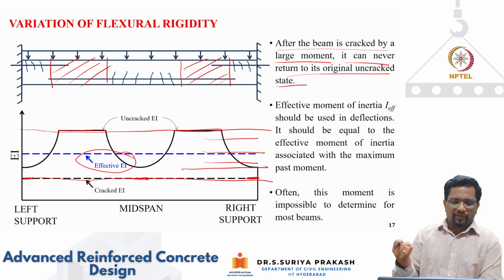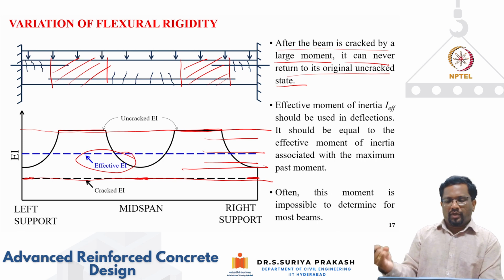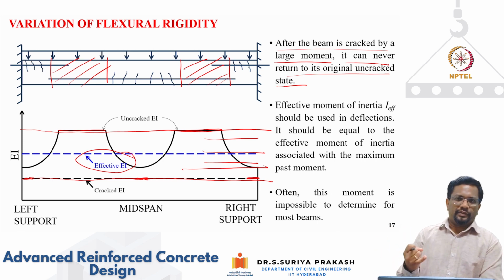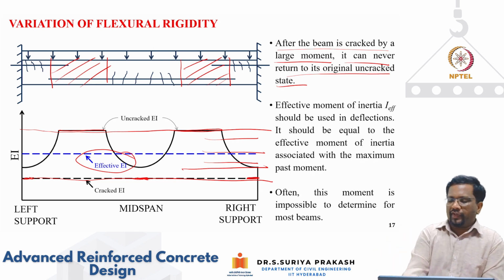So what we are trying to say from this is that I cannot use the uncracked flexural rigidity, or I cannot use the cracked flexural rigidity. I have to use something in between. So the effective moment of inertia, I effective, should be used in the calculation.